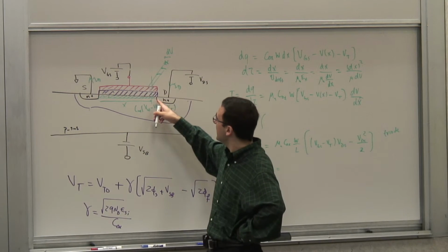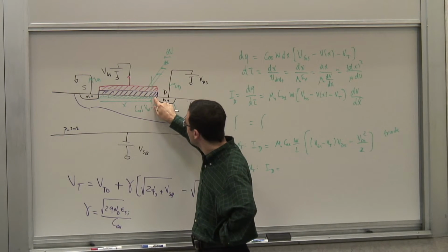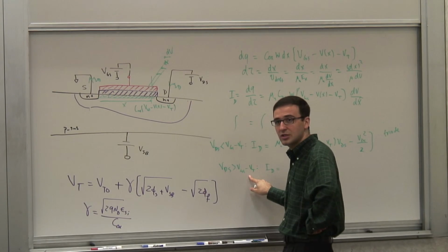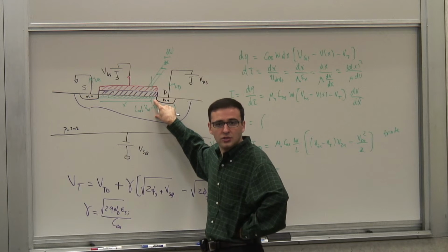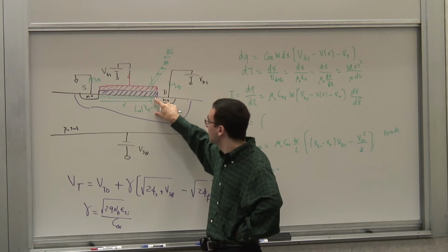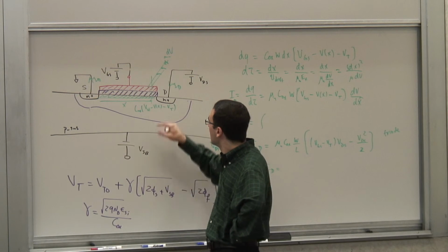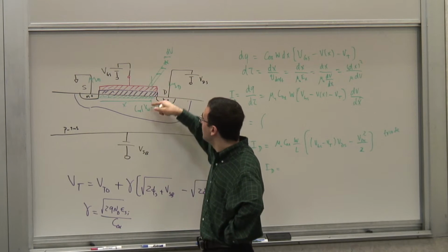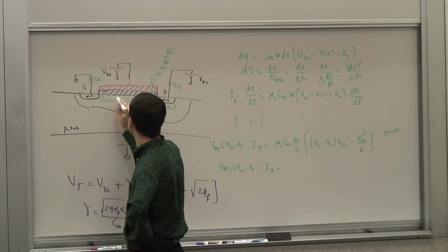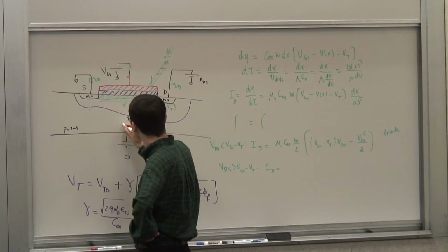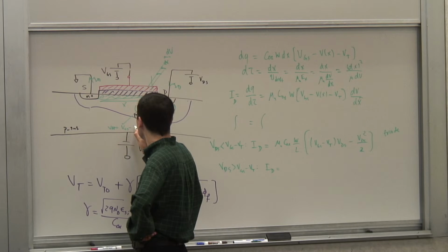Well, to calculate it, we have to consider VT, the voltage drop across that, right? Across this channel. And now if you go beyond that, what happens is that this point is shifted. So what happens is that you have a channel only up to a certain point, but at that edge, the voltage of that point, V of x, is always VGS minus VT.